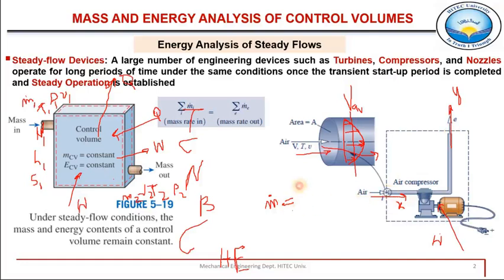And for that case, m dot is given by rho, the density of the fluid, multiplied by the cross-sectional area of the passage perpendicular to which this fluid is moving, multiplied by the velocity in that particular direction, V. That is the mass flow rate, called the one-dimensional flow form of the mass flow rate balance.